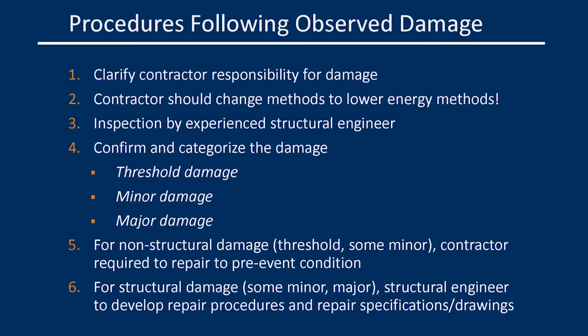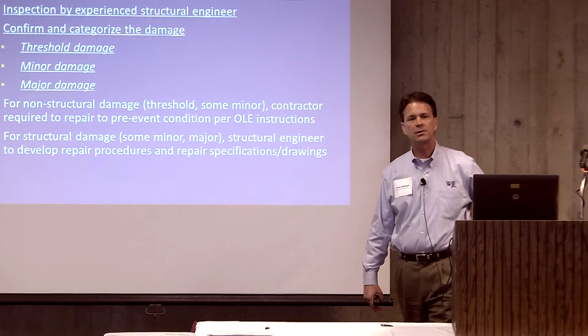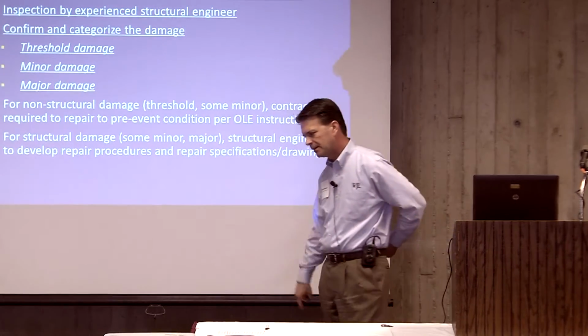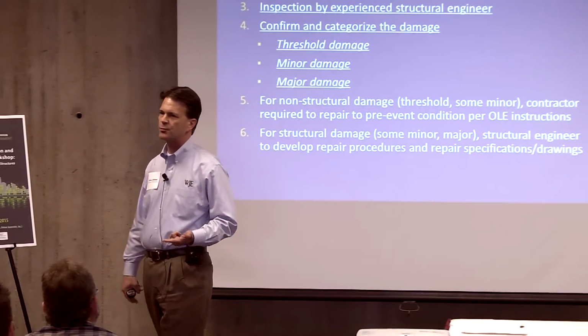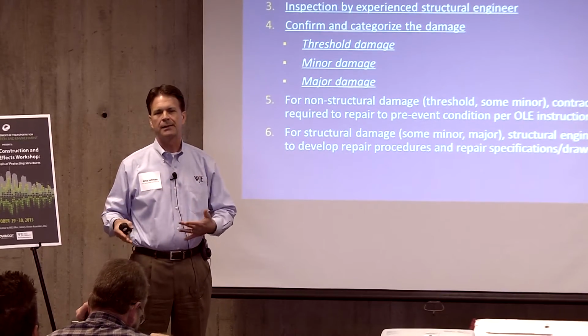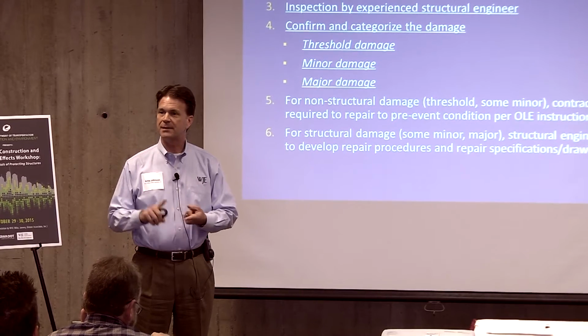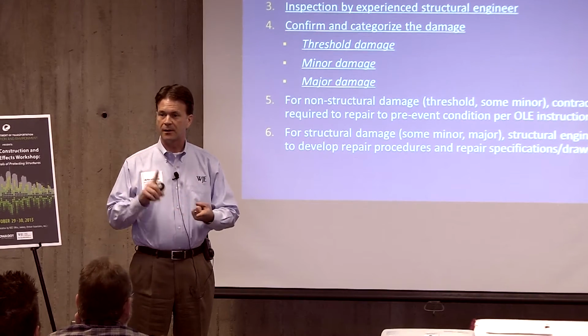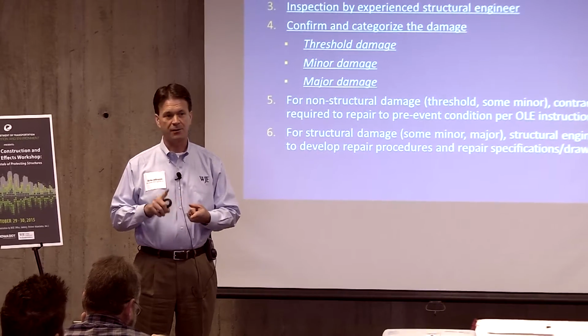And I would like to suggest that you categorize the damage into these three categories, and I'll define those on the next slide, because these are really the definitions that have been used in the vibration literature way back, from the U.S. Bureau of Mines testing. And if you can use these same definitions, you've protected yourself in the event that this becomes litigious or controversial, because the limits are set up to prevent even what kind of damage? Threshold damage, and that's got a very specific definition in the literature, and there's research behind it.